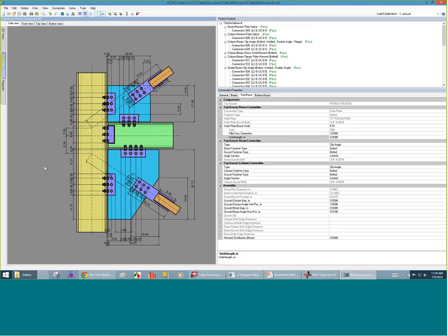In this case, I was demonstrating me being the engineer. I also have Tekla Structures on my computer, so I'm doing double duty. I'm doing the design of the structure in Tekla Structures, laying out all of the locations and all of the Tekla Structures information, as well as doing the RISA connection model. That doesn't have to be the way you do it. If you weren't going to be doing both of those tasks, you could have just taken it right over to RISA connection, saved it, didn't make any changes to that model, and sent it to your engineer. Your engineer would run through all of what I just did, make the needed changes, and then send it back to you. All you need to do at that point is just replace the file that you have.